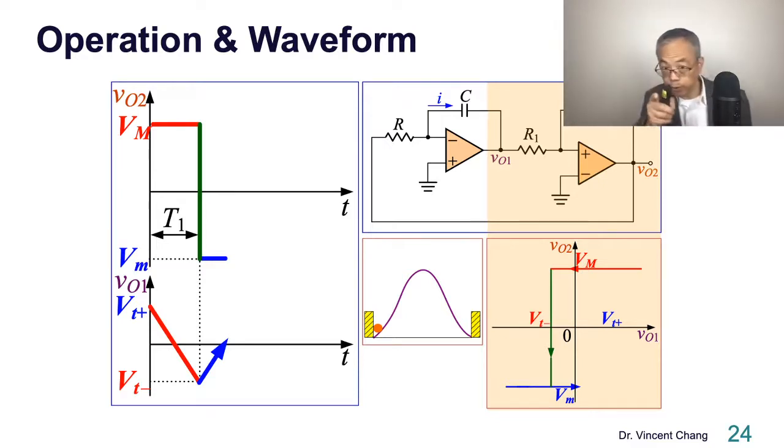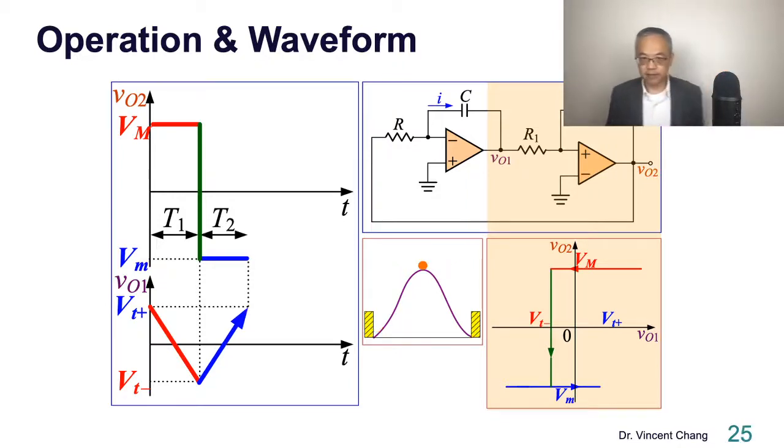You see the blue and the blue. And this blue, the right-hand side of the slide, there's the arrow. And associated with the blue arrow on the left-hand side of the slide has the same meaning. So when VO1 goes up, who do you compare with? Because it's blue state, you compare with the blue threshold, the upper threshold, the VT positive, okay?